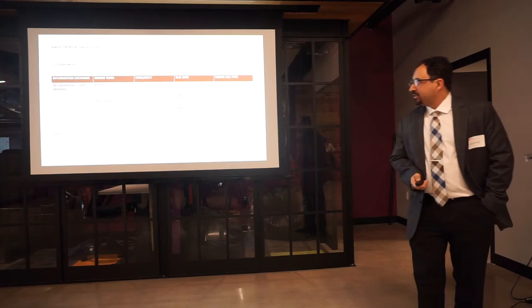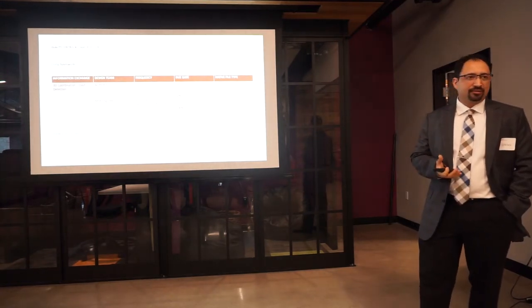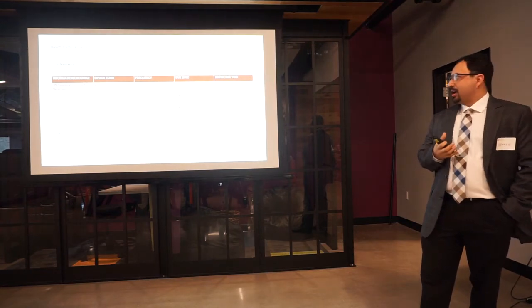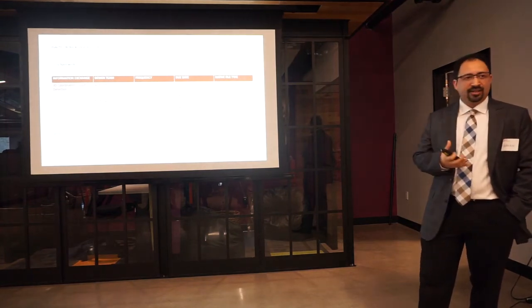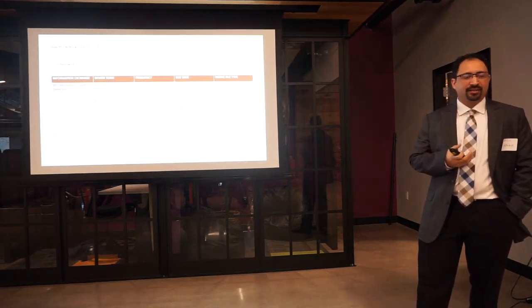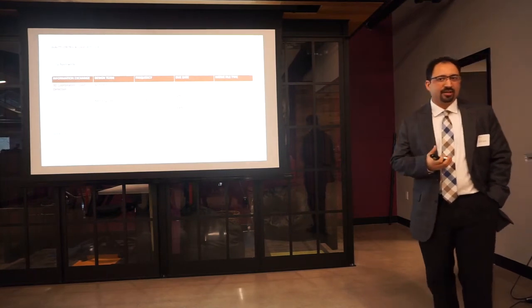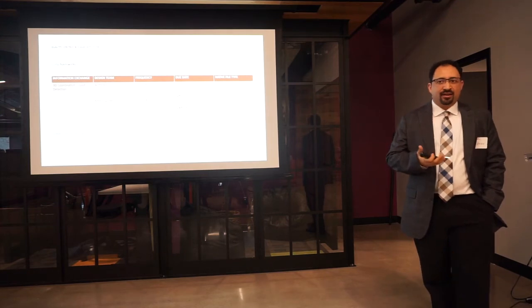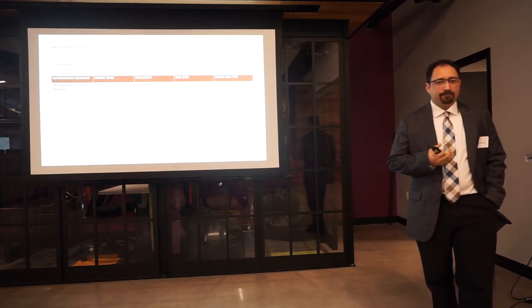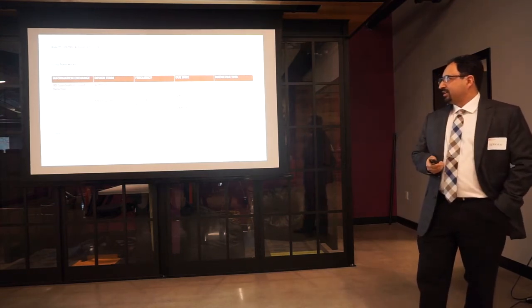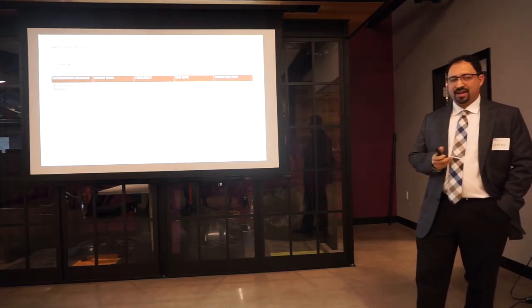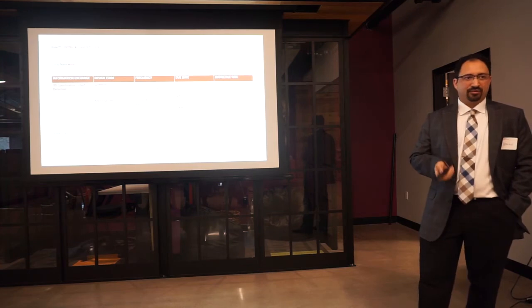So we used Navisworks as our primary tool. Navisworks Managed 2015 was the exact one. And we had clash detection coordination meetings every 2 weeks. Well, occasionally we'd have one every other week, depending on the phase of the project. The intention being that at the end of every week we'd have a list to review with our team.